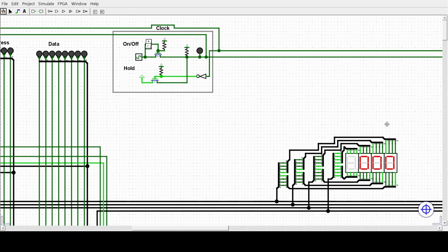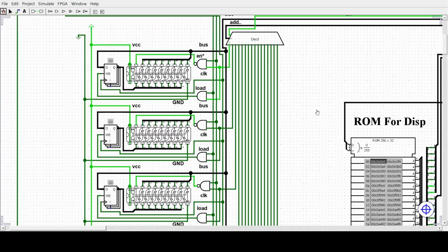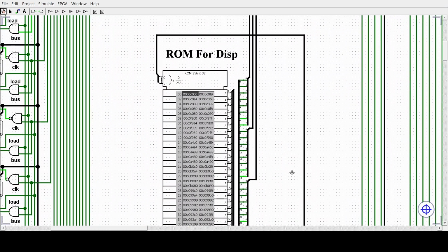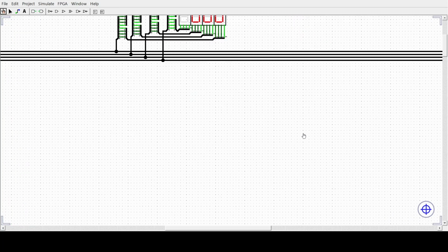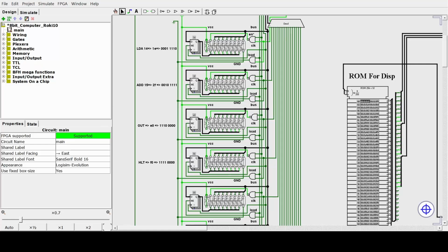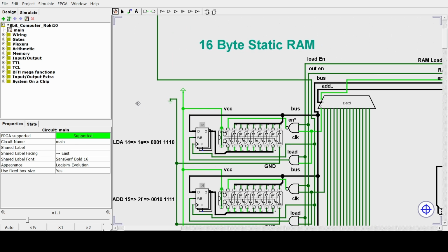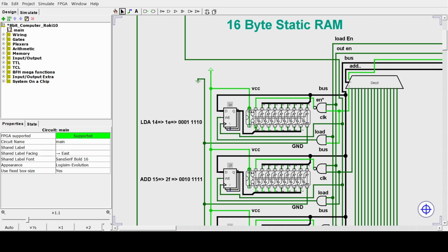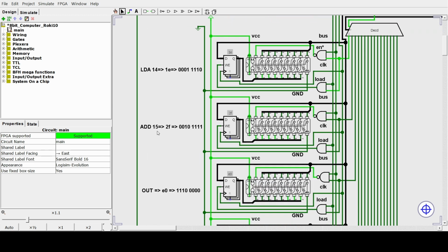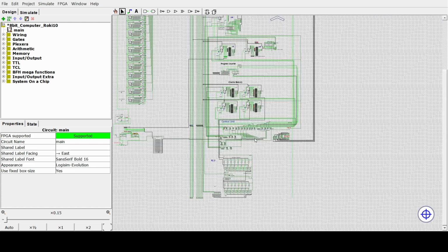Now let's look at the specific instructions we are performing. I am using software called Logisim Evolution to input binary numbers in RAM or memory. This software provides a simple method. Simply, we write down hex codes and the binary instruction is put in the register, which makes it easier to present the instructions. We are going to perform an addition of two values stored in memory.